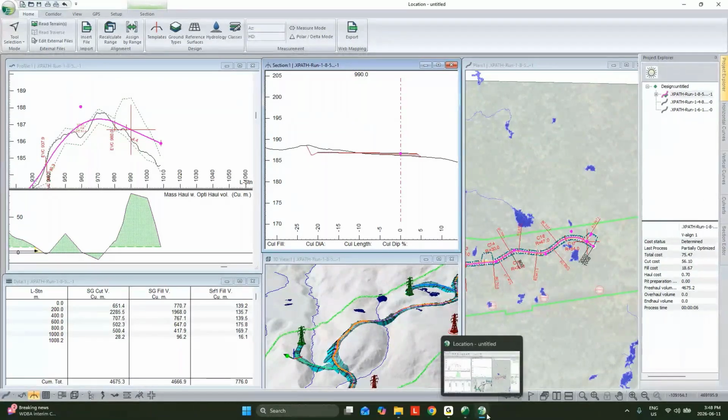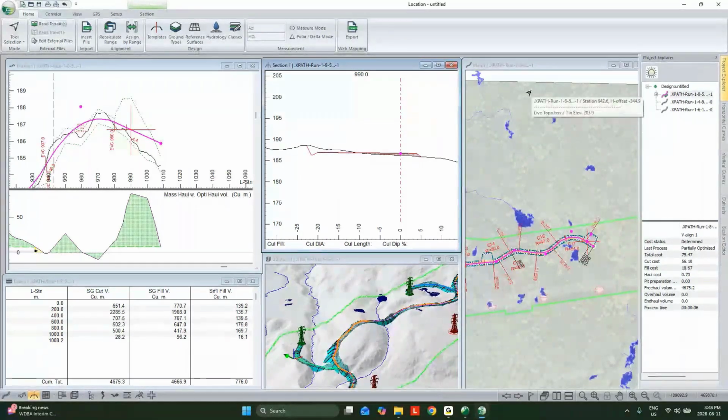So I think the most common formats for field notes brought in would be shape or KML, and you can just insert that into terrain, and you can add labels or symbology to treat that however you like. So show a label that shows all your notes in it. So as you're designing, you can see what you want to see without having to dig through that other data set. I don't have a good example for this one, otherwise I'd show it.